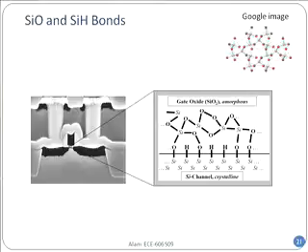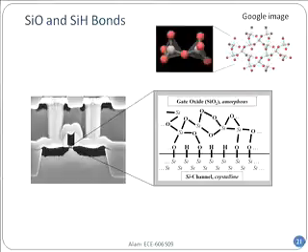So this is the amorphous structure of silicon dioxide, this random network of tetrahedra. This is not diamond lattice. Diamond lattice doesn't look like this. This is a tetrahedra, but it looks very different from diamond lattice, right? So that's silicon dioxide. So anytime an oxygen is missing, that's a trap. That's where all those charges were being trapped before, in what I was showing you earlier. And in each of the tetrahedra, the oxygen is red, and that's being shared between 2 silicon, the ash-colored atoms. So you can see why this is called silicon dioxide.